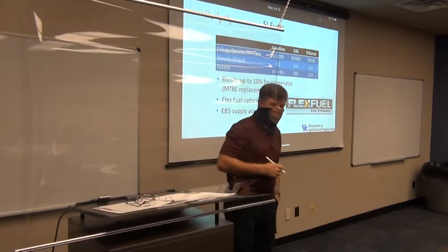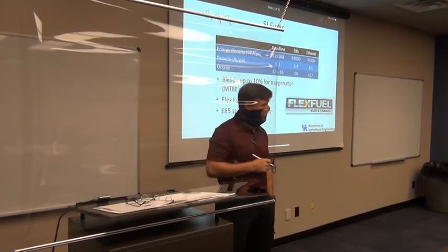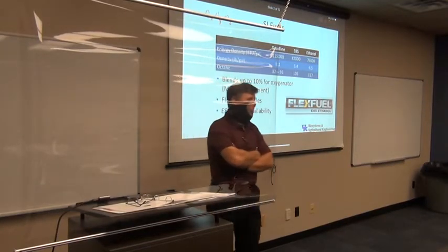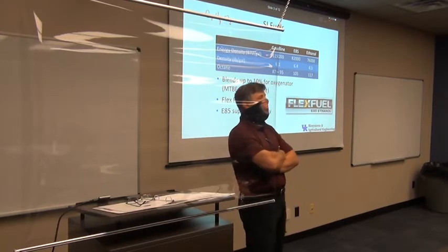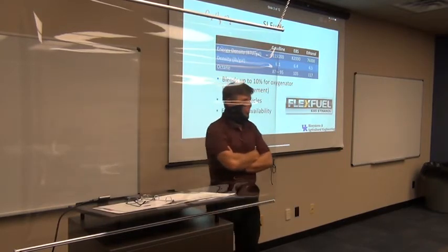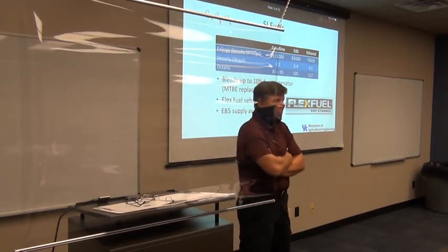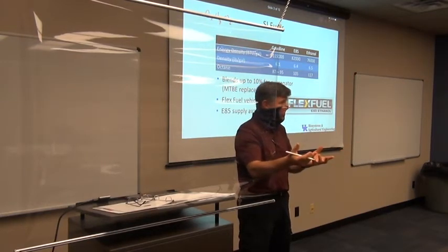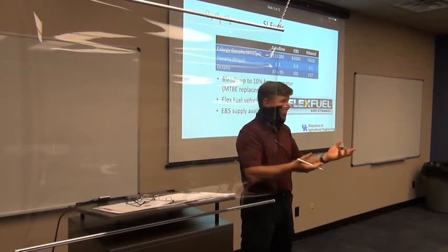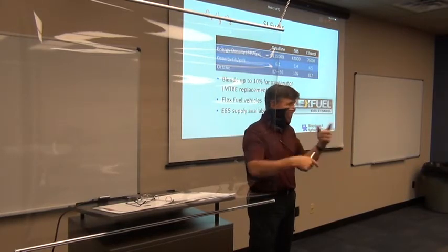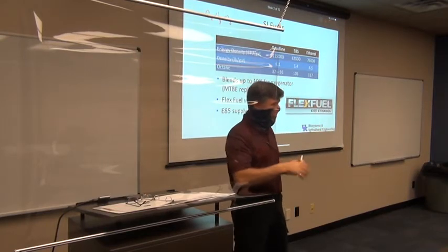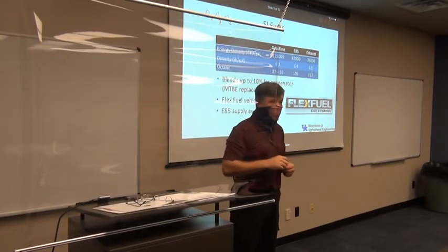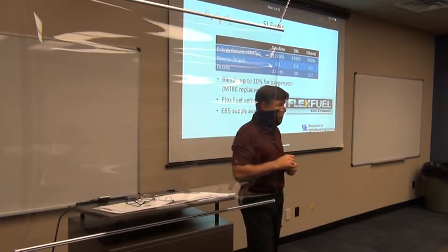How does that help us? How does having oxygen in the fuel help us in the engine? You get cleaner emissions. Okay, why? Because you don't need as much air. When I pull air in, what am I pulling in with the air? Mostly nitrogen is what's coming into that engine, and the oxygen comes with it that I burn. So the nitrogen is in there, and then it gets hot, and it combines with the other stuff, and you get nitrous oxides and all the weird stuff coming out. We'll look at emissions later on, and spend a little more time talking about where that comes from.